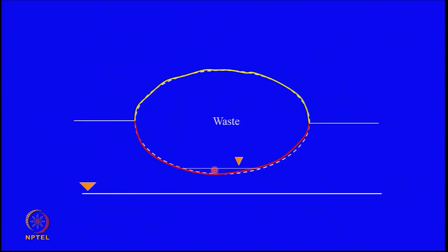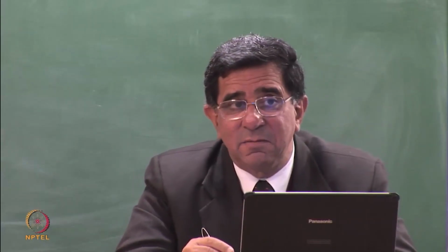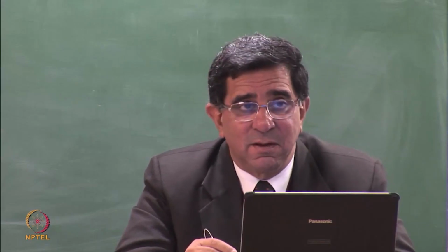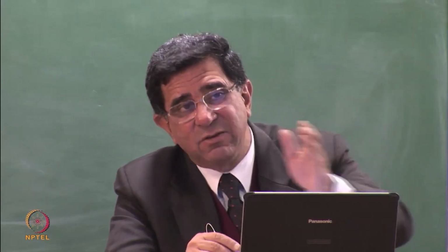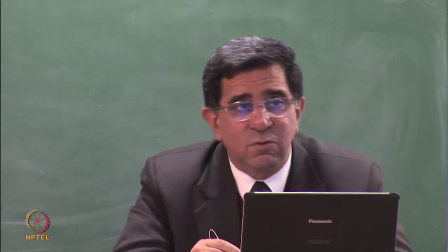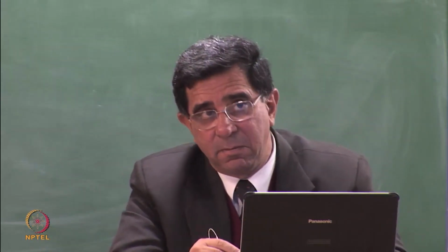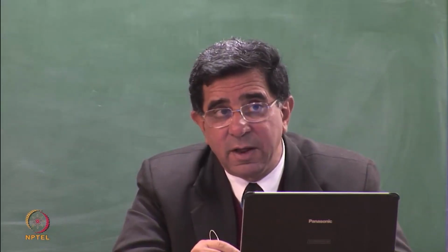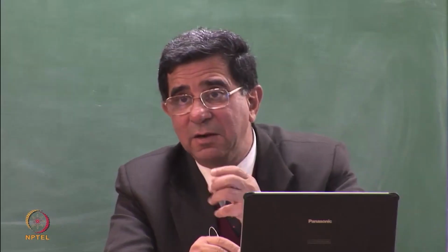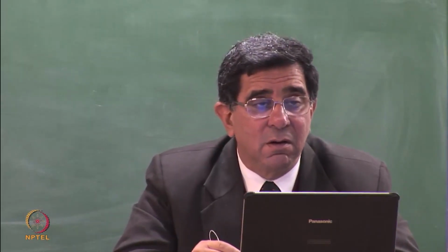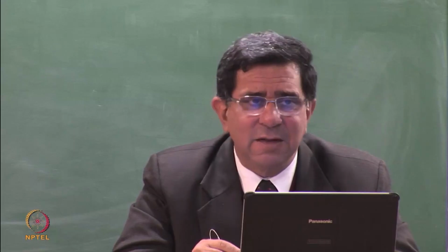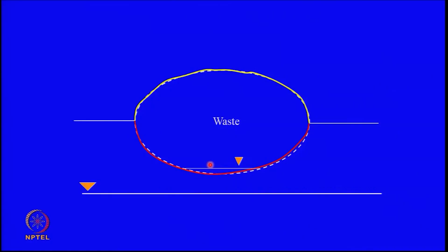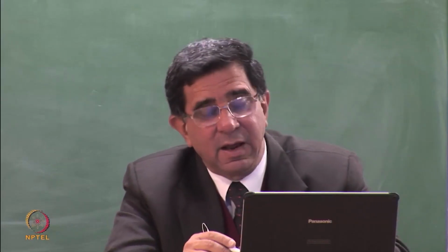But I've often given you this example that the roof that we make on top of us is only as impervious as the drain pipe which is operational. That means the roof is impermeable as long as the water falls on it and drains off into a drain pipe. Suppose the drain pipe of the roof gets clogged, then the water gets ponded on the top. And if you have a ponding of the water on your roof for a day or two, you find wet patches coming under the roof. So that means though concrete is impermeable, supposedly so, it means that it has low permeability, but it has some permeability. So if my leachate is going to remain ponded on this impervious material, say for a month, then I have a problem. It will leak.